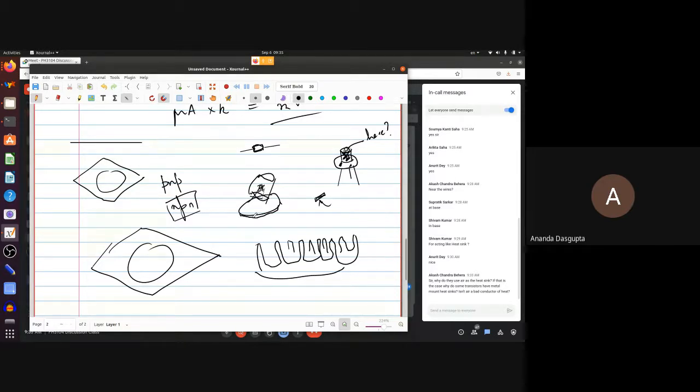On the other hand, actual heat sinks like this, which are called heat sinks as separate entities, are made of metal. But even there, you have these pieces taken away. And that serves two purposes. One, it allows you to use less of the metal, which is going to be expensive. The other is it gives you more surface area.